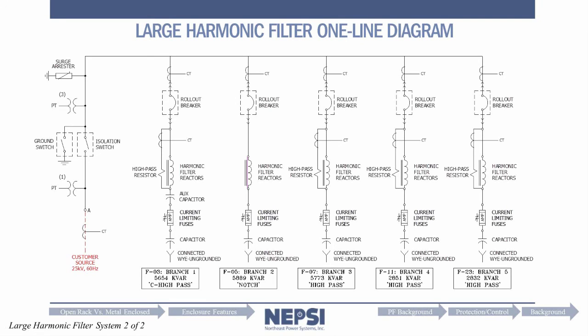And finally, there's blown fuse detection, which can be done in several different ways. We could use neutral voltage sensing or neutral current sensing in a split Y cap bank. We can also use direct fuse sensing. So other than R, L, and C, there's still a lot to do with specifying a harmonic filter that you need to be concerned about.